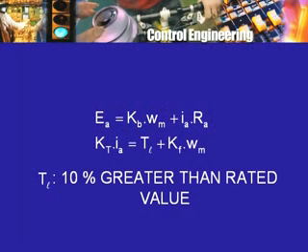So suppose that happens. EA in our very simple drive, we are just getting 230 volts DC and we are not doing anything about it. So EA is 230, the parameter values, let us assume, are known exactly. So if you look at these equations, then what is going to be the effect of this change of TL from 30 Newton meters to a higher value?